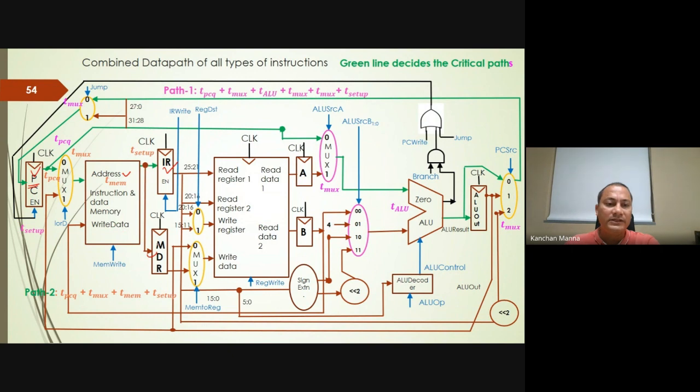And for this case, this one would be the destination, and then this ALU, because we're getting the value from ALU out. So this would be the source for LW, and this would be the destination. Got it? And same way, after that, we're reading that value from the register file, and we're storing it in A and B register. So that time, this is the source, and this is the destination. In the earlier case, this is the source, and this is the destination.